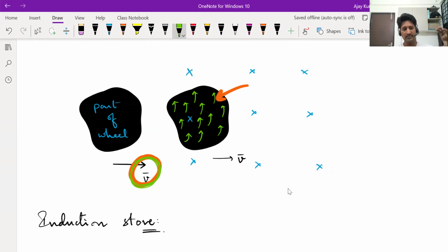Okay. So when this conductor moving with a speed v enters into a magnetic field, or let's say it moves inside a magnetic field, the kinetic energy which is there with the conductor gets converted to electrical energy of the eddy currents, which further gets converted to heat and is dissipated. So kinetic energy is getting used up and released as heat. If kinetic energy is getting used up, it means the speed is reducing. That is how magnetic braking works.